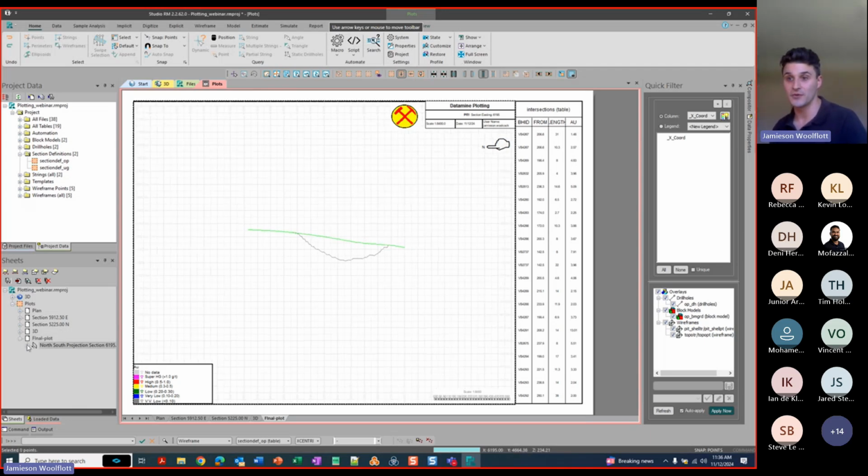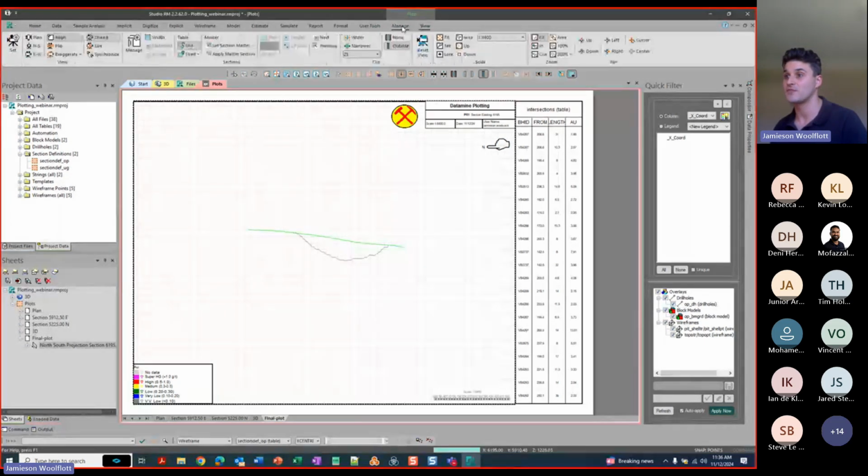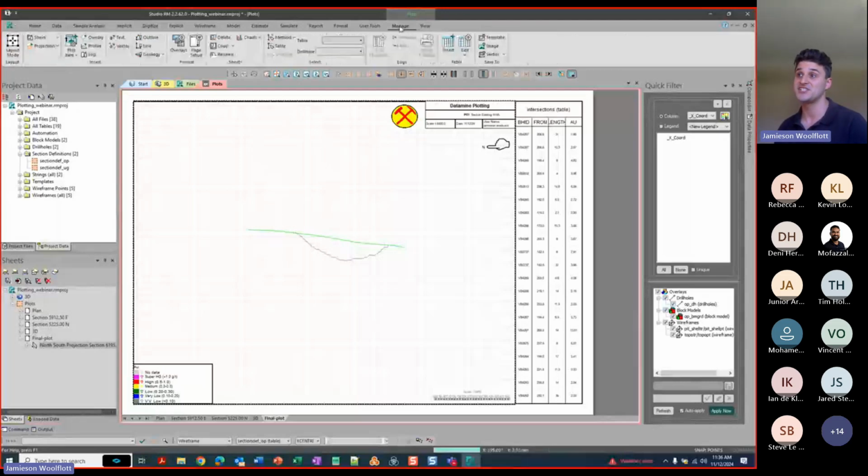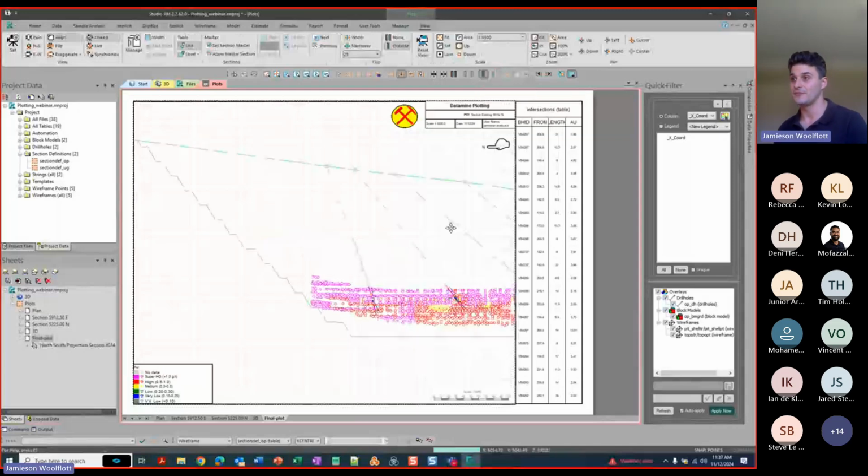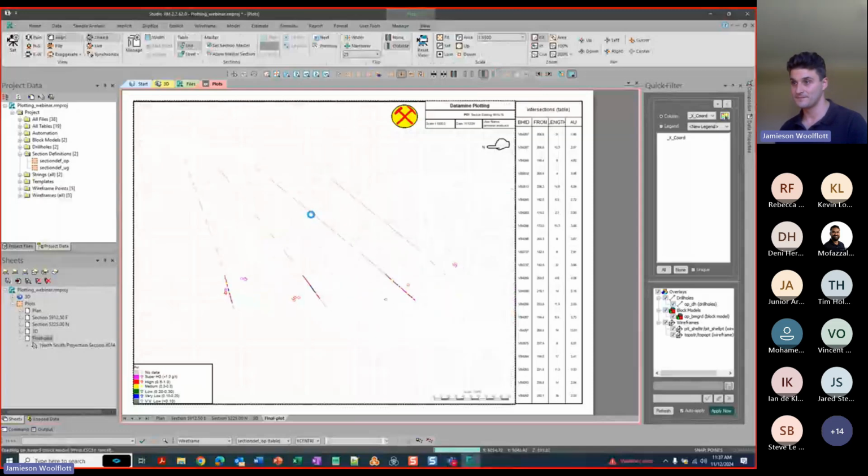And what I might do is I'll just bring it back to, so when we come back into the template, all we need to do is pick a section. So we go manage, view, next, and that will jump us to a section. You can see all my data. Pick the scale. Unfortunately, the template doesn't save the scale. And recenter everything.